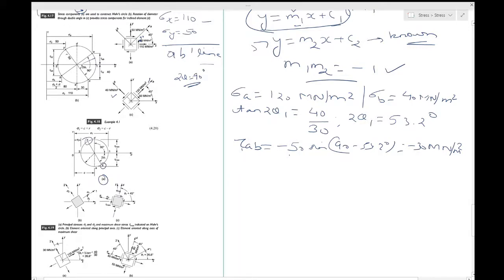You have already done that part, and the end points of this diameter, this point on your circle is 1, and this point on your circle is 2, and please call them 1 and 2 as they are. They will be important at some point. So what can this value be said to be? Sigma 1. This value can be said to be sigma 2.